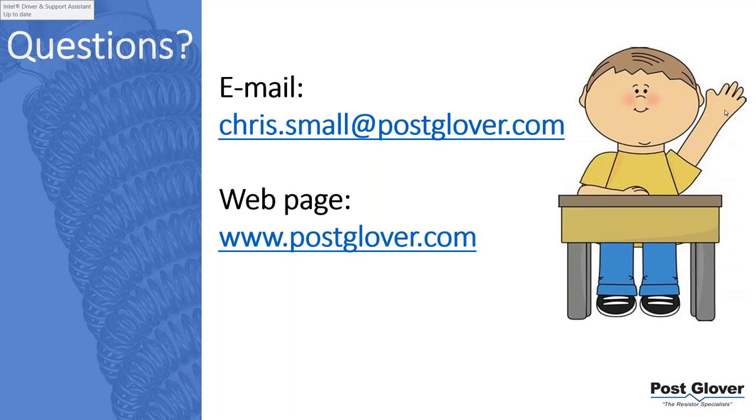Okay. One of the questions, and there were quite a few questions, thank you all very much for posing them, and I guess I'll say paying close enough attention to know what to ask. One of the questions from earlier in the presentation was, does NFPA and/or IEEE 1584 allow consideration of the reduced ground fault current in the hazard determination? He said he's aware that the calculation is based on three-phase fault current, but does it not take into account the fact that if you limit to 5 amps, you have less potential for a hazard?